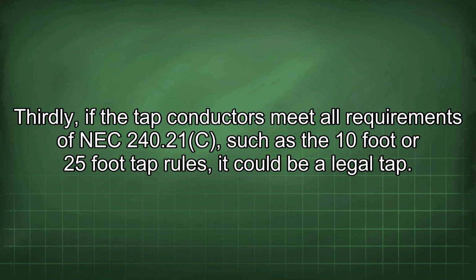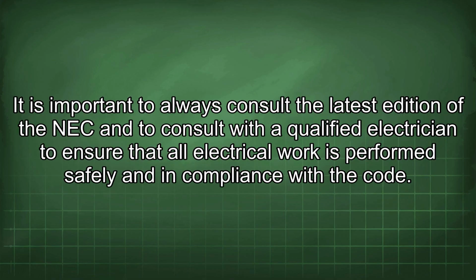Thirdly, if the tap conductors meet all requirements of NEC 240.21(C), such as the 10-foot or 25-foot tap rules, it could be a legal tap. It is important to always consult the latest edition of the NEC and to consult with a qualified electrician to ensure that all electrical work is performed safely and in compliance with the code.